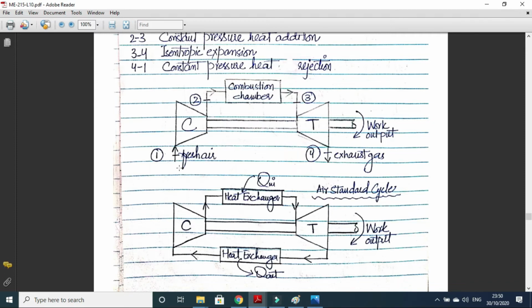Like we can see here in the aeroplanes, fresh air is taken into the compressor. The compressor compresses it, so by compressing it, its pressure increases, but its temperature also increases. So this high pressure and moderate temperature air goes into the combustion chamber where fuel is supplied and combustion takes place, and the air becomes high temperature, high pressure here. Now these high temperature, high pressure exhaust gases go into the turbine, strike the turbine blades, and the turbine rotates, and we get the power output. And then we also have the nozzles, like these high exhaust gases.